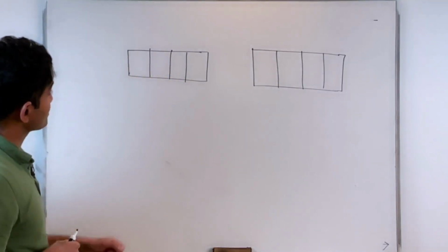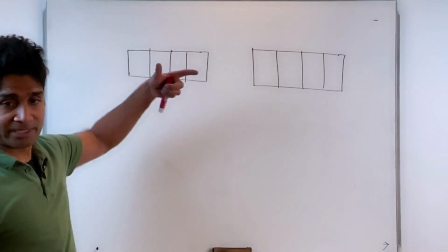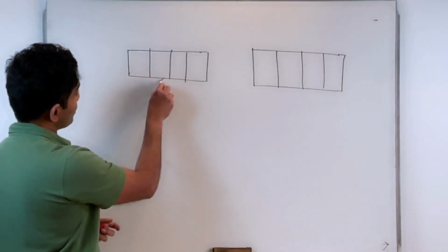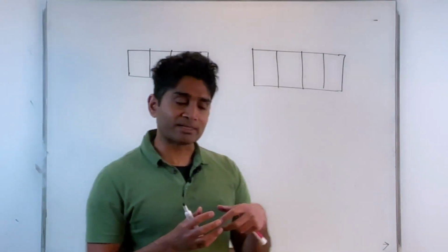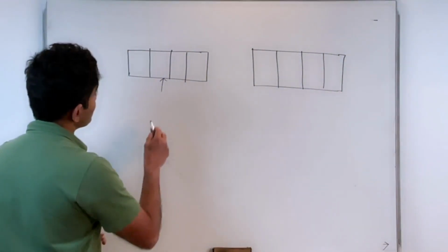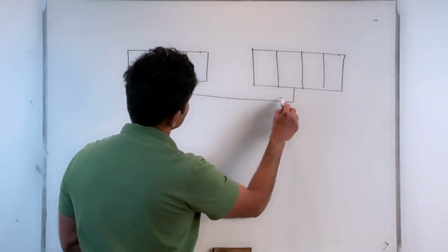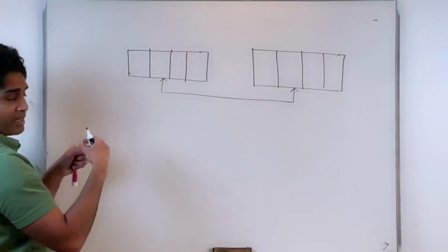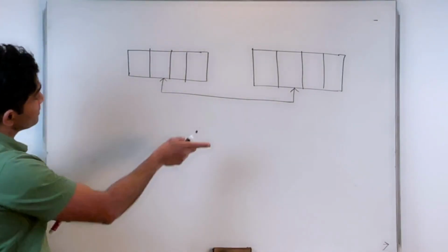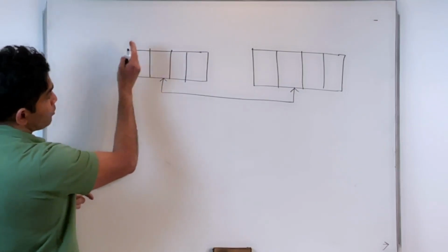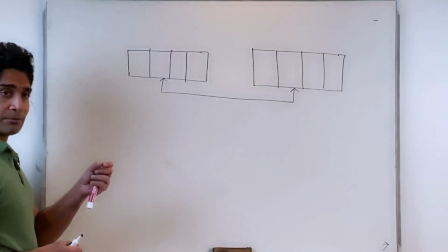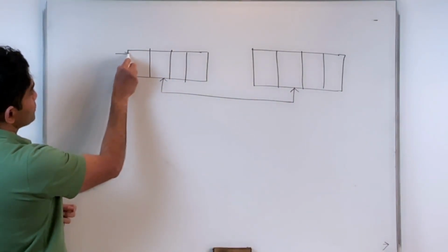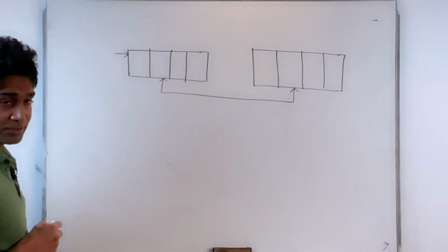So again, as we have already discussed, each of these blocks is nothing but a D flip-flop, and these are all internally connected. That means if I show the clock to one flip-flop, that clock is internally connected to each of the flip-flops. Okay, same thing here. All right, and because that's the shift register, although I do not show the explicit connections, they are there. It's basically shifting one bit to the right with each active edge. Okay. All right, so that's the input to the register.